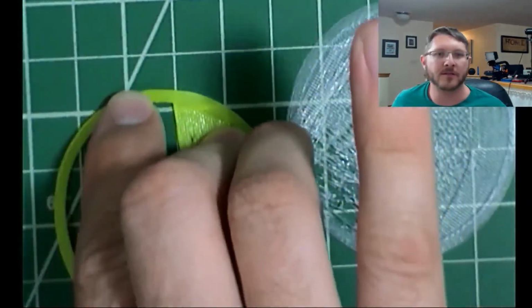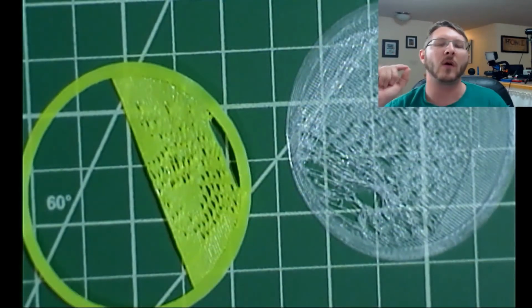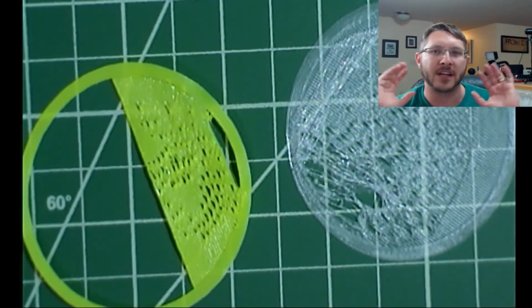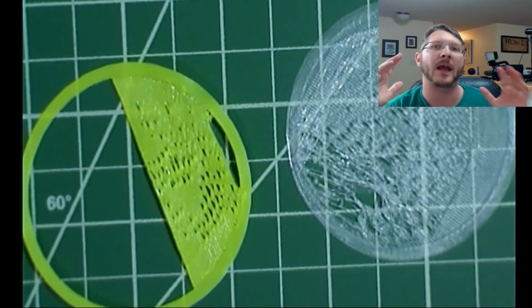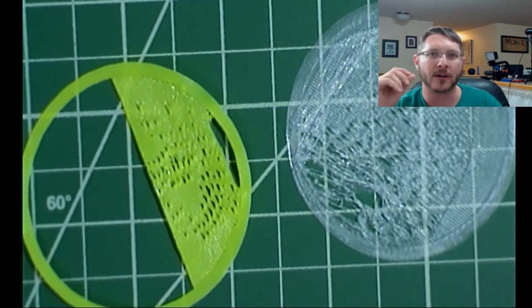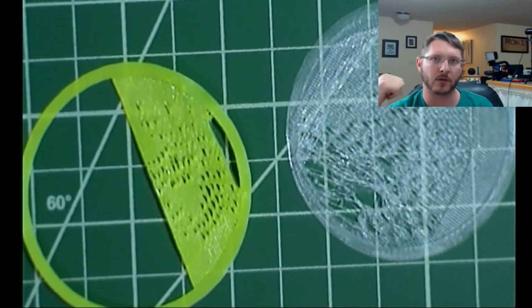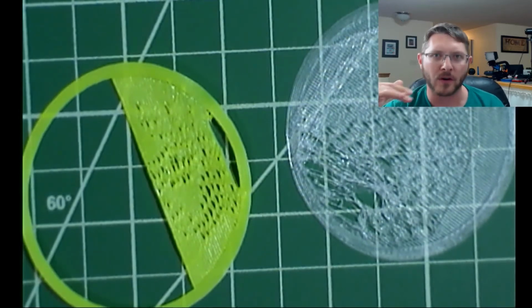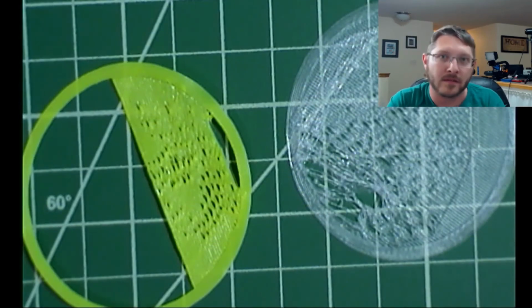This first few layers, that was exactly what the whole thing looked like once I heated it up a little bit more. So you may not necessarily need an adhesion fixture. You may not necessarily need the hairspray or glue or something like that if you have one of those mats. You know what I'm talking about. They're a hard mat that's sticky on one side. If you have a Wanhao, you know what I'm talking about, or the Tevo Little Monster. If you have one of those style printers that has that type of a sticky deal for the bed, then a lot of times you just need to increase the heat. So just increase the bed heat if the bed heat can be increased.